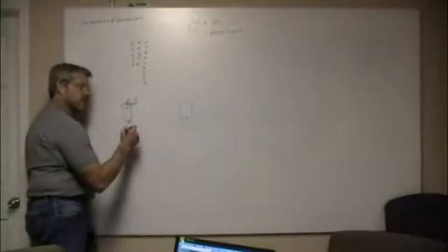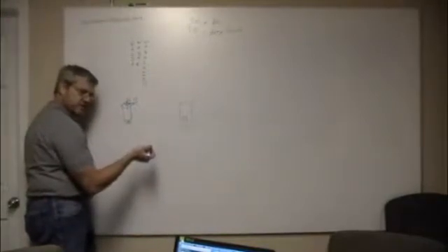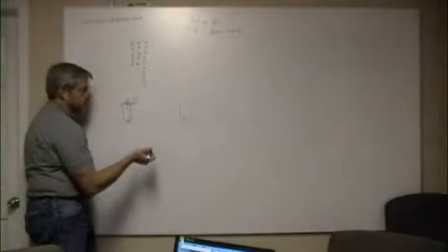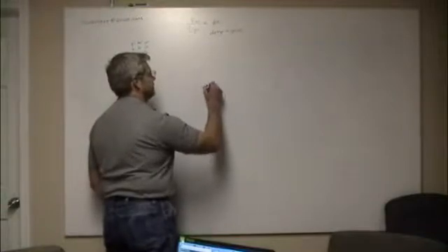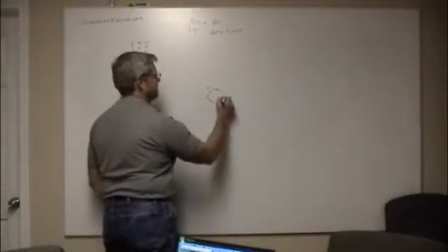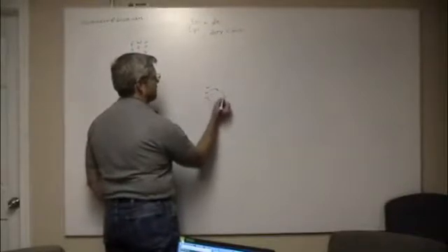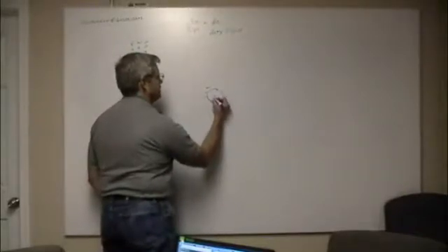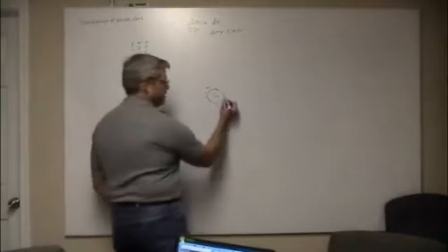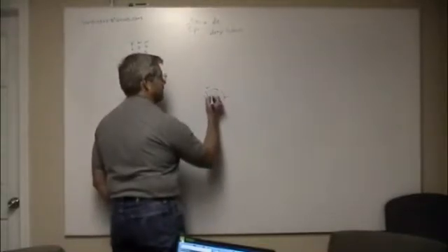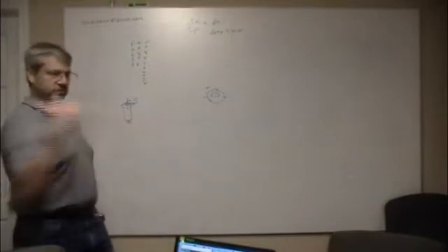And remember we talked about an H-bridge, I think, at one point? Did we talk about an H-bridge? Don't remember. Don't want to go there yet. I'm going to go there now. An H-bridge is a way of steering current. If I have a standard DC motor with 2 leads, and this one's normally called plus and this one's normally called minus, for instance, that will cause a clockwise rotation of the shaft. And if I reverse them, then I'll get a counterclockwise rotation of the shaft. So that's how I can make a DC motor go both directions.